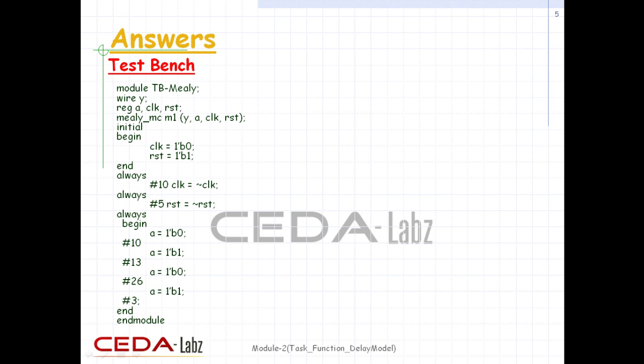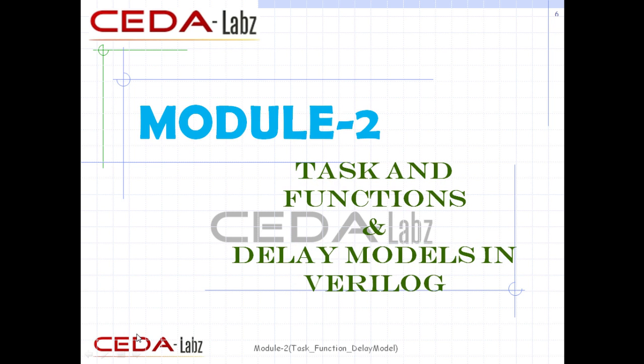Here is the test bench for the same. As we used to do: module name, port declarations, module instantiations, clock initialization and generation, input conditions with delays, and termination via endmodule. Let's come to our next topic, which is tasks and functions and delay models in Verilog.